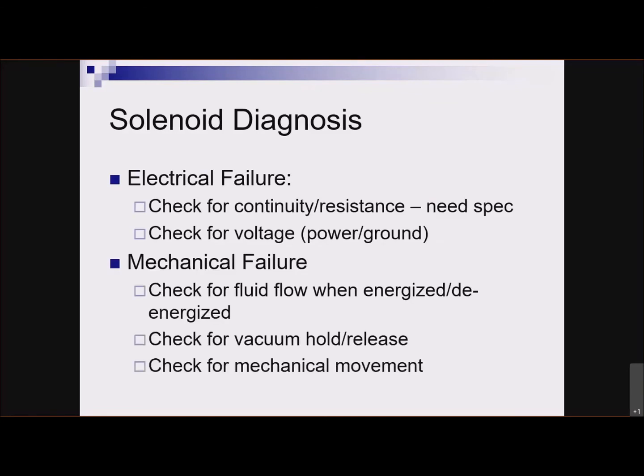So how do I diagnose a solenoid? Well, for electrical failure, check for voltage, both power and ground. Usually the easiest way to do this is to unplug the solenoid and put what's known as a Noid light in. I'm assuming Noid is kind of short for solenoid, right? But what it is, it's a little light that you can plug in place of the solenoid.